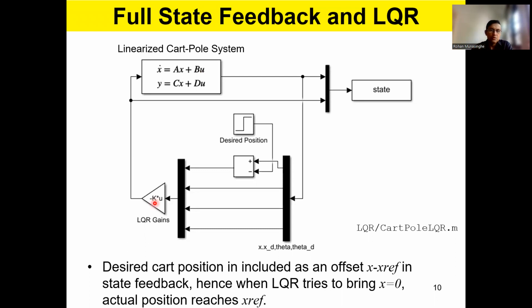you don't need to simulate the linear plant. Not necessarily. You can actually have the entire nonlinear plant over here, because that is the reality. For the controller design, you use the linearized model because you can't use the nonlinear model to design the controller. But once you have the controller and want to simulate the plant, I think it's good if you use the nonlinear plant dynamics for the plant. Remember that.